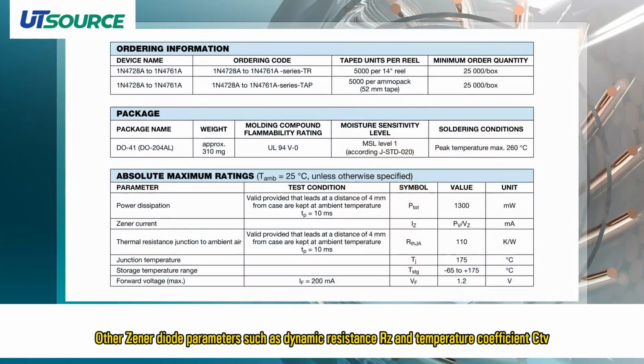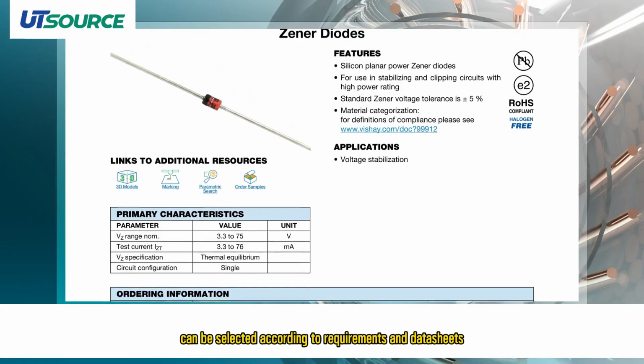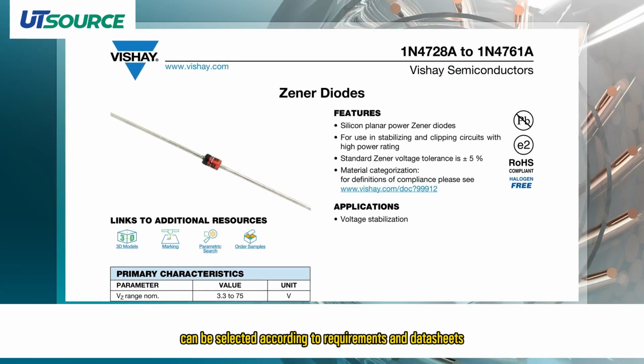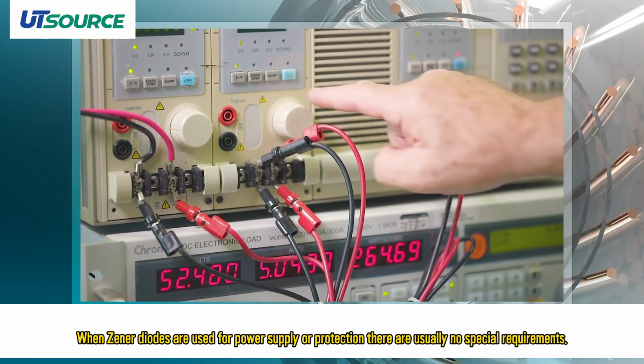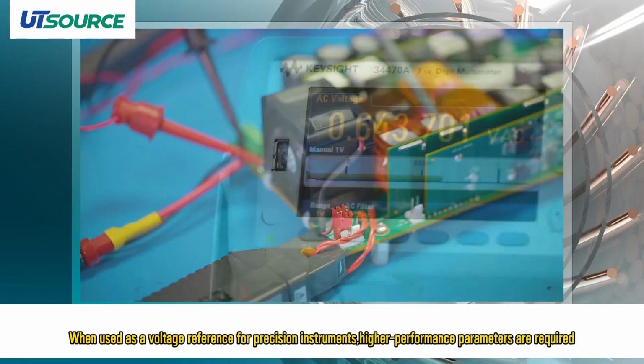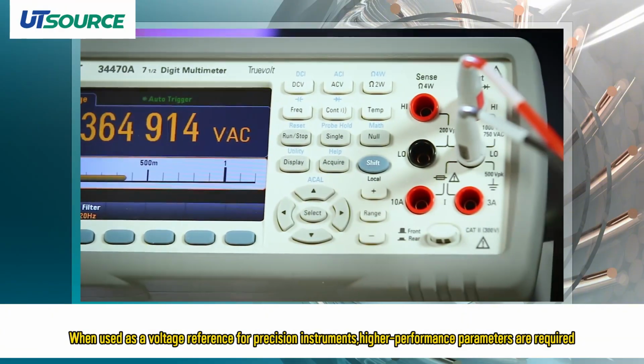Other Zener diode parameters such as dynamic resistance Rz and temperature coefficient CTV can be selected according to requirements and datasheets. When Zener diodes are used for power supply or protection, there are usually no special requirements. When used as a voltage reference for precision instruments, higher performance parameters are required.